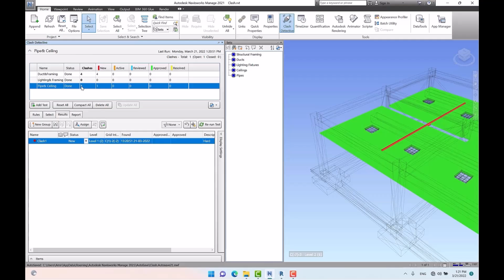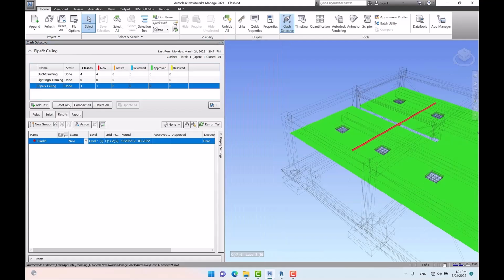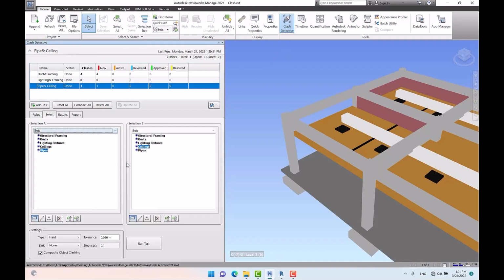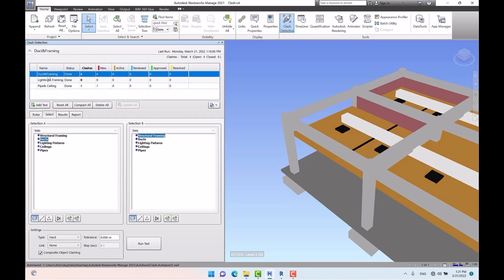However, some may want to specify a specific value for the tolerance when running a clash test for each of the clash groups. But normally, we specify 3 to 5 centimeters for the tolerance, and it is acceptable. So our first way for having correct test criteria in selection is creating or saving selection sets by using find items, and I think it is the best and ideal way. But what is the second way?